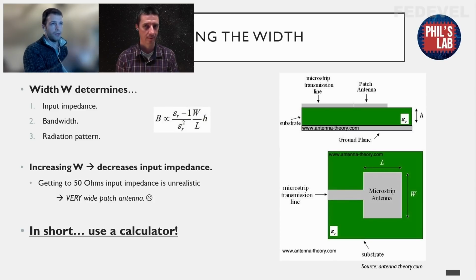It's also a reason why a 4-layer board, with a dielectric very close to your patch antenna, might not be a good idea, because the dielectric might be 0.1 millimeter, 0.2 millimeters. And since the bandwidth scales with the height, you're going to divide your bandwidth by, I don't know, 10 or something, compared to a 2-layer board. So on a 4-layer PCB, usually you would like to remove layers 2 and 3, for example, and only leave the bottom layer.